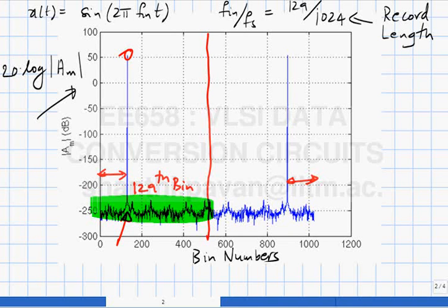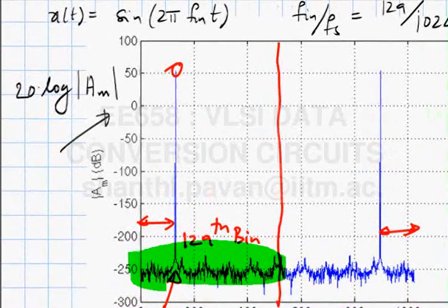So when you take the log of 0, you must get minus infinity dB. But please note that you are dealing with a finite precision machine, right? So even though you have a perfect sine wave, it is rounded off to 32 bits of precision. So this is basically noise. The Fourier components of the real sine wave are not exactly a pure sine wave; it is a very, very pure sine wave with some round off noise because of finite machine precision. So this is happening because of that.